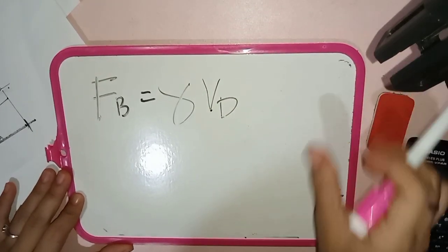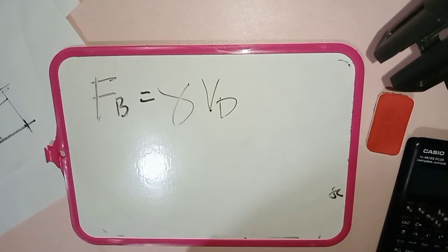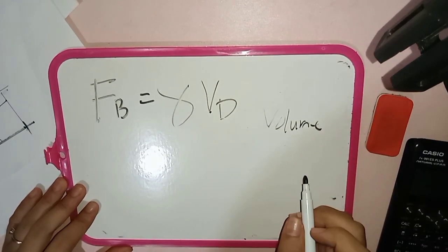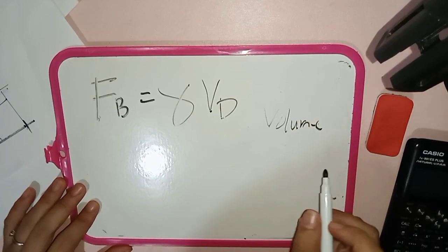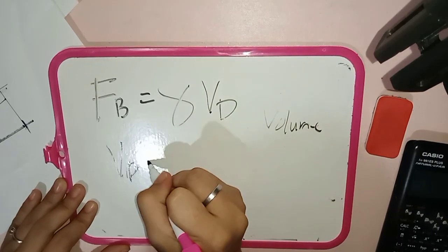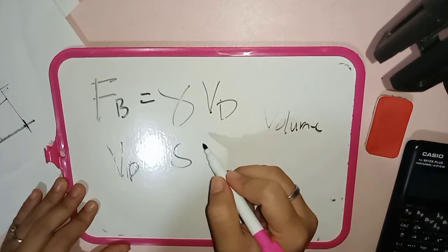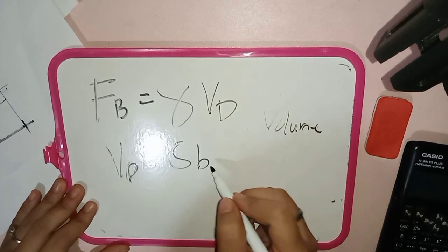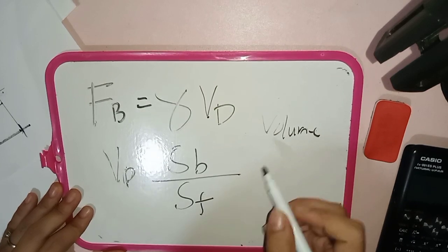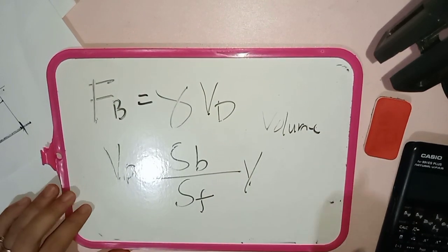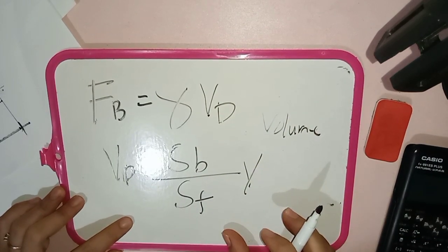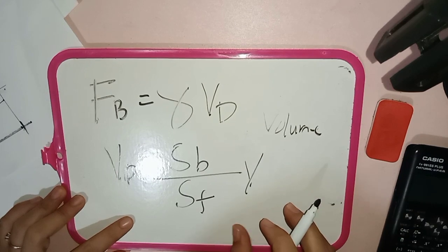Then for a homogeneous solid body of volume V floating in a homogeneous fluid at rest, the volume displaced is equal to the specific gravity of the body over the specific gravity of the fluid, or water, times the volume. The next formula is if the height has a constant horizontal cross-sectional area, such as vertical cylinders, blocks, etc.